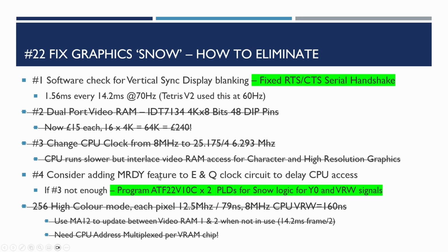respond. But in fact, in this particular case, what we can do is to use this to delay the CPU from accessing the video RAM, so that we can let the video RAM finish doing what it's needing to do and then let the CPU have access to it after that. So that's what the diagrams and things we did in the previous video was all about. I'm just going to quickly show you what changes we need to make to the in clock circuit, and then we'll have a look at programming the PLDs.